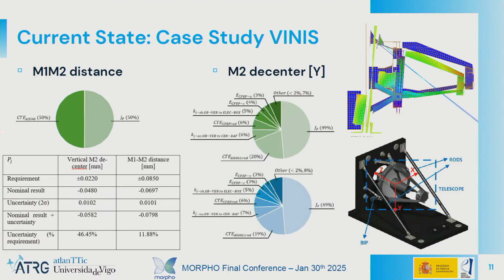Okay, so now we can see that a large part of our uncertainty and possible loss of performance is here in these rods, and we can go directly to the constant of thermal expansion of these rods and act on that. So initially we wanted to make a cheap design, but now we cannot go for that because it's really hindering our performance, so we can go and change them to titanium.